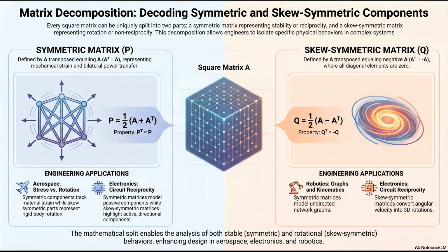Okay, what are they? The first is actual mechanical strain. The aluminum or composite material is actively stretching, compressing, and shearing. Like the molecular bonds are actually being tested. Yes, physical deformation. But the second phenomenon is rigid body rotation. A vortex of air might cause a section of the wing to locally pivot or shift its spatial orientation entirely. So the rigid body rotation is just movement through space.